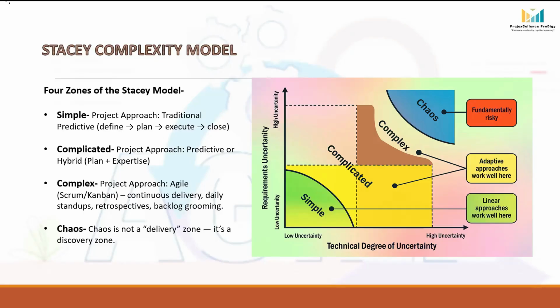These requirements are clearly defined. The project team knows what the hospital wants. But for the technical complexity, you need to match the generator to existing building load and wiring. Ensure the generator integrates with automatic transfer switches. And you have to consider safe fuel storage, ventilation, and vibration control. And you have to meet the local compliance codes and safety inspections.